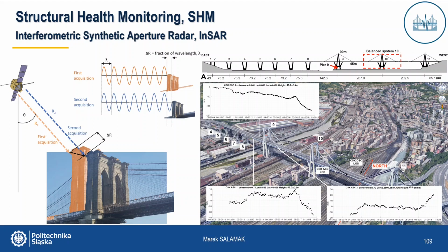It turned out that the changes in the grade line of the road near the later collapsed pylon were already visible in 2015. Besides, between March 2017 and August 2018, there was a significant increase in structural changes in several bridge parts, indicating that at least part of the structure was already in a critical condition.